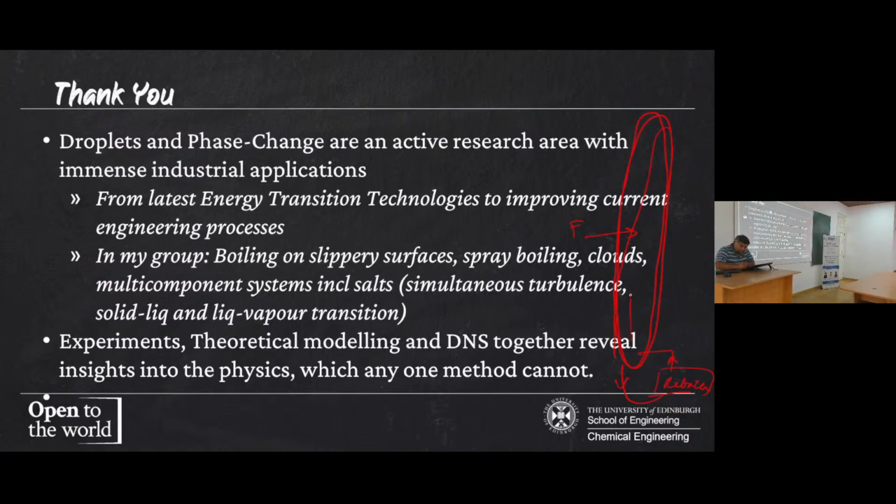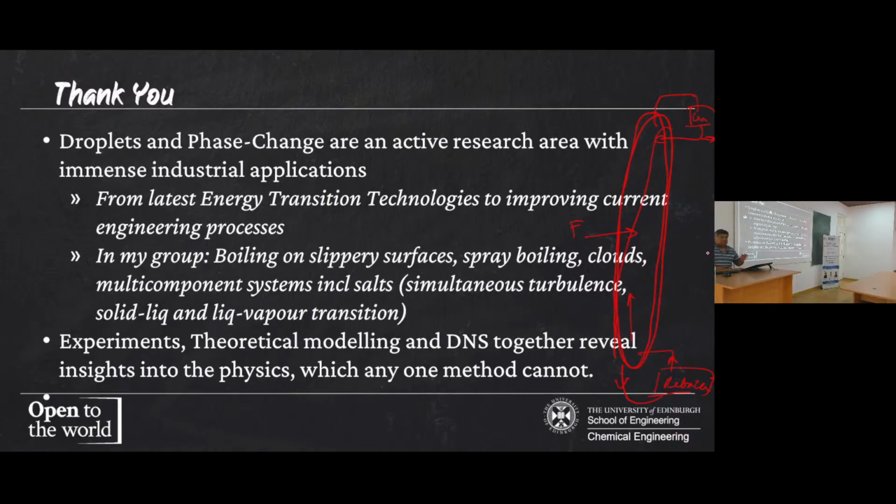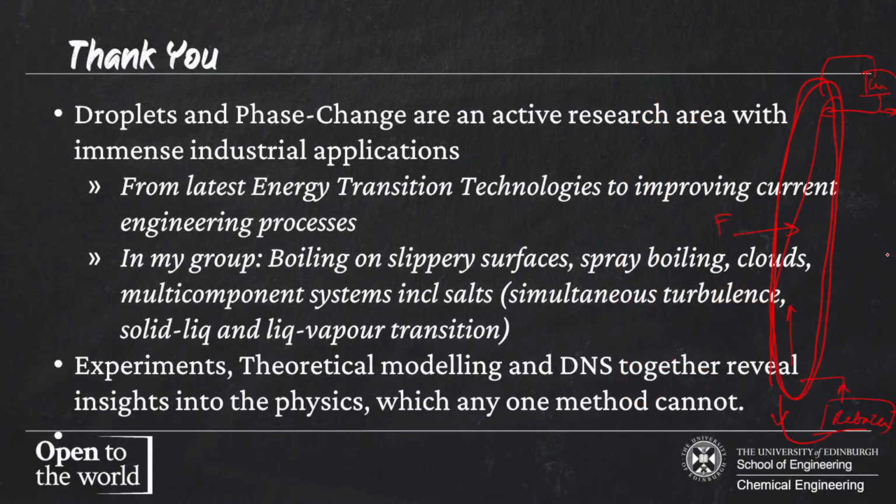So the gas goes up, and then over here you have a condenser, and all the purified components go out of the condenser and the reboiler. Distillation is fundamental to any processing. You will not have your petrol, you will not have your clothes, you will not have any refined product without distillation or any of these methods. We will not have a modern society without it. And all of this is a function of phase change, whether it is forming gas or forming liquid. So this is a fundamental problem for everyone.